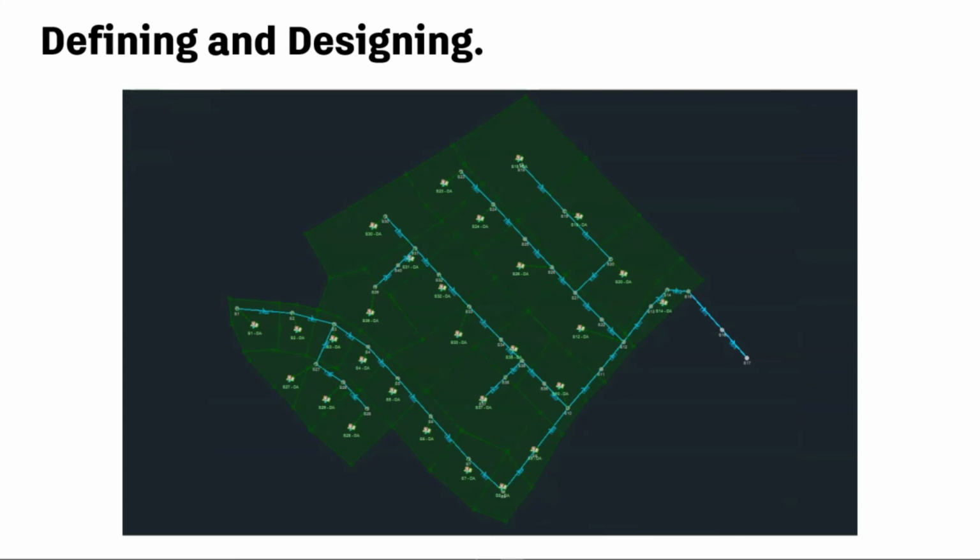Then, using our skill and judgment, we start to design a potential layout of these pipes and manholes, as well as identifying the catchment areas and allocating them to manholes they will drain to. Accurate delineation of catchments is crucial as it directly impacts the volume of runoff originating from these areas. For instance, factors like the time of entry introduce a delayed effect, creating a lag between rainfall on the surface and its entry into the manhole.